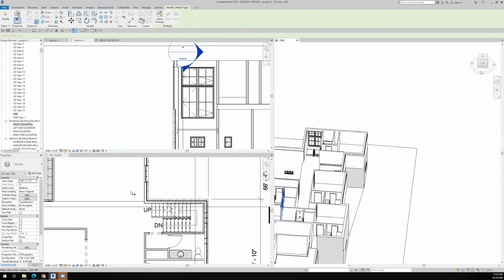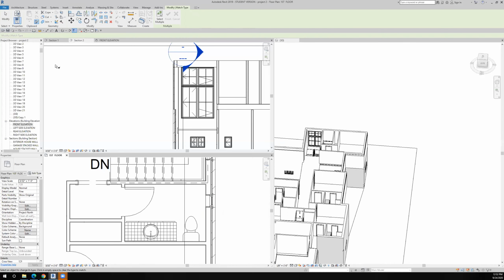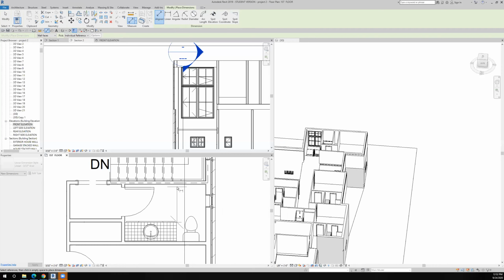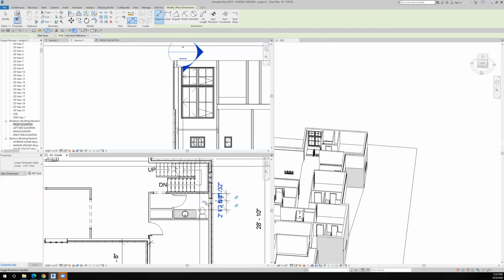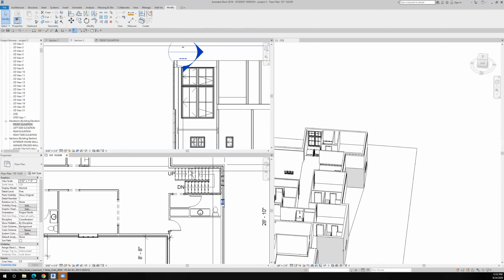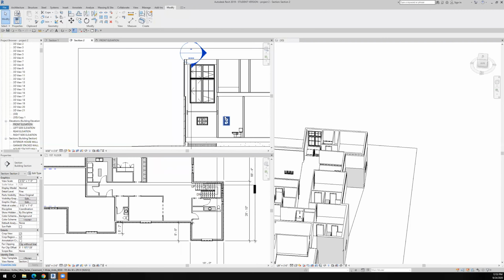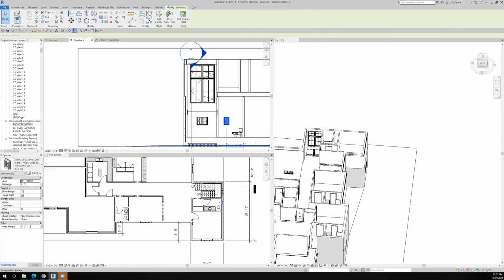And then the next thing to do is simply put this window in. And I'm going to say that the best place for that window to be is centered on the opening between the countertop and the wall. So now we're looking good there. Let's go over and take a look at it. I want that window to be 7 foot tall. So I'm going to change my head height to 7 feet.